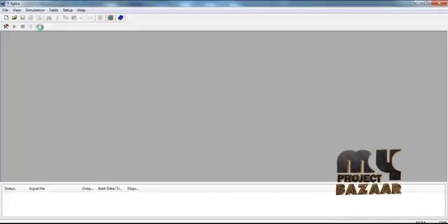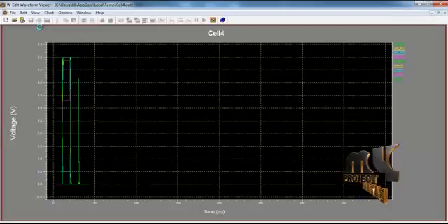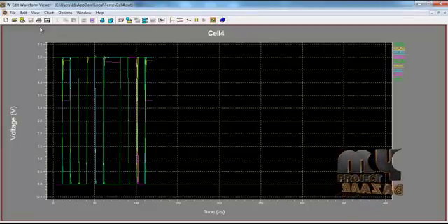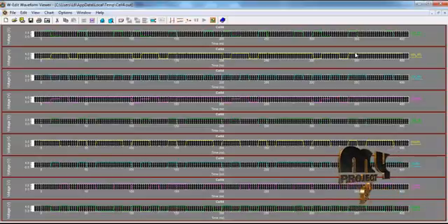This output produces the T-Spice and the W-Edit waveform files. T-Spice is the background running process, and the waveform edit file produces the output variations for the voltage level. We apply three input data bits, A, B and a carry input, passing into every adder circuit, and the carry is passed to the next stage's carry input. The first 3-bit sum and carry output, the carry output is passed to the next 3 input adder structure. This passes on to the overall final output. These are the sum and carry outputs for the overall 8-bit adder circuit diagram.